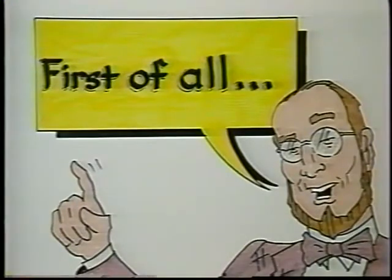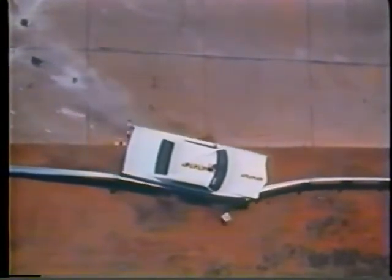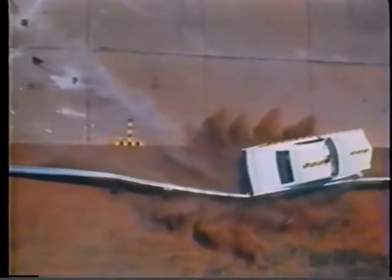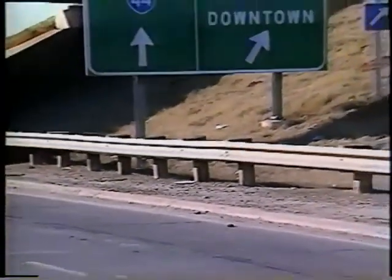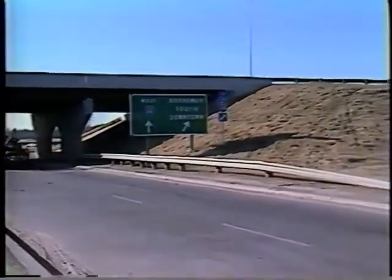First, let's review the major functions of the two systems. W-beam strong post systems are semi-flexible traffic barriers that are designed to stop, slow, or redirect any vehicle that hits them. The barriers are made up of three basic parts: an end treatment, a standard section, and a transition section. All three components are required to make up a system. How these parts are individually designed will depend on the terrain and location of the hazard.